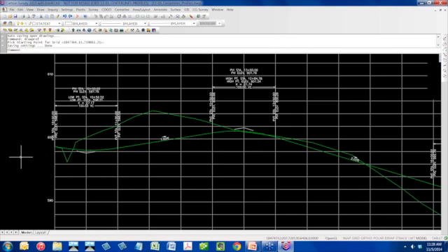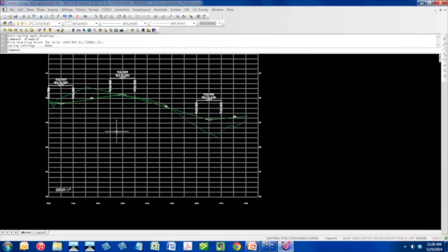So we've got just a couple other things. We're probably going to go about 45 minutes here total today. So we've got both of these. Let's now show, you know, I had one profile drawn in on this grid, and I have a second profile, and in this case, because I didn't really like the grid I started with, I just decided to redraw both profiles on a new grid, erase the old one out of the way. But maybe I've already taken the time and the effort, and I've got this grid, this profile exactly like I like, but I want to add in another profile such as pipe crossings.